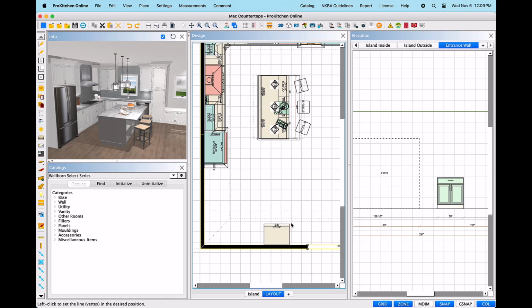To change the shape of the countertop, left-click once on the desired point. Once again, the countertop will look as if it has disappeared temporarily until you move the mouse. When moving the mouse, the outline will appear black once again, and you may move the point in any direction to change the shape of the countertop. Left-click to secure the new shape and the mouse will again become a crosshair, and the countertop will be outlined in red.